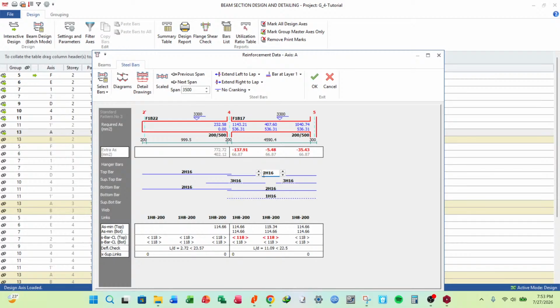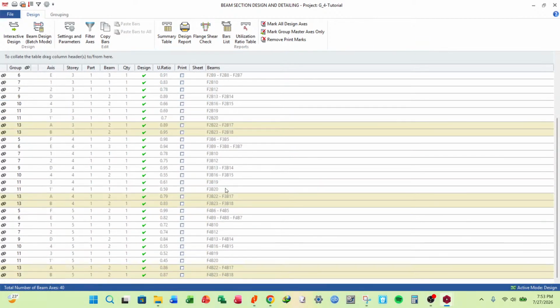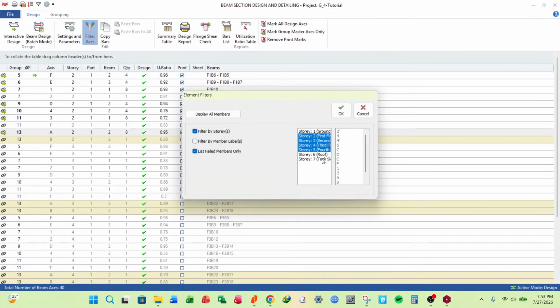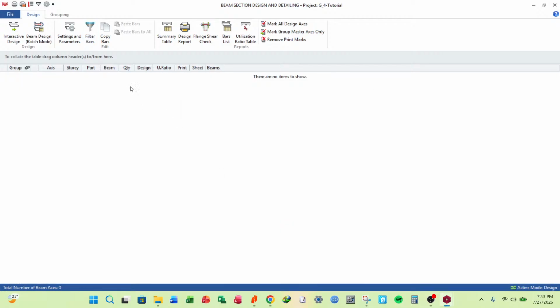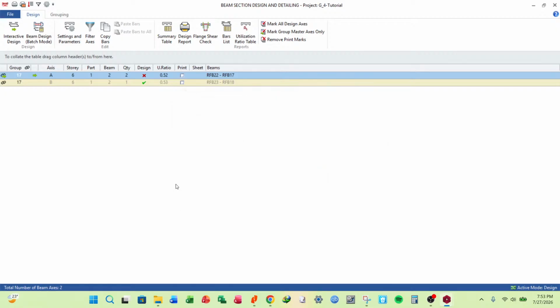So even up, you're going to have 2 continuous bars and an extra one at the top. And we are done. So this is all with the floor beams. Okay, you can filter out then the roof. Let's start with the tank slab and do the same to it. The tank slab has nothing displayed, which means it's getting its reinforcements with the other, with the downer beams.